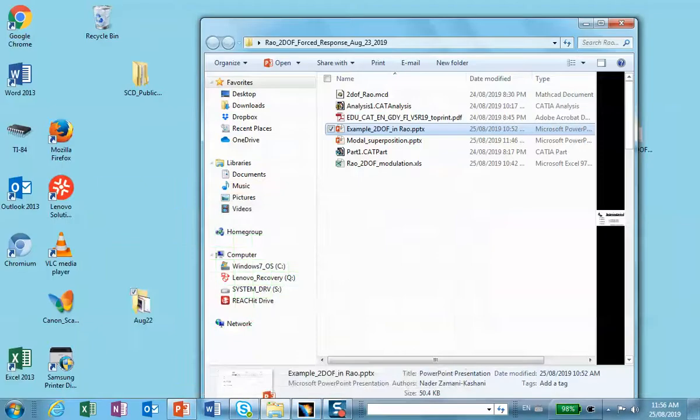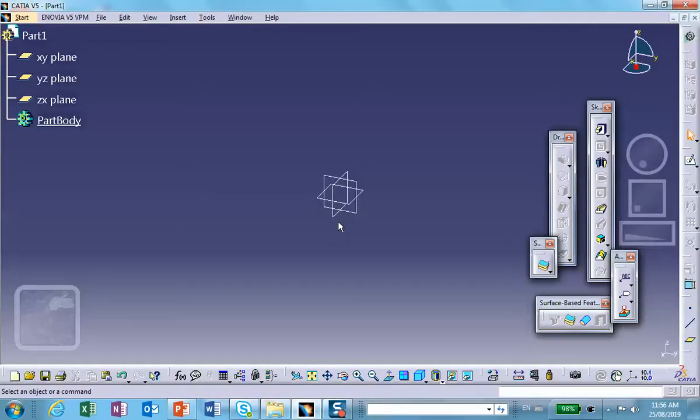Here's my Catia. The unfortunate thing about the way this has to be done in Catia, at least as far as I know, maybe wrong, is although you don't have any solid geometry, you don't have any elements in the traditional sense, such as beam, bar, shell and solid, tetrahedral, if you don't create a geometry with those things on it, you cannot model this problem as a lumped parameter system.